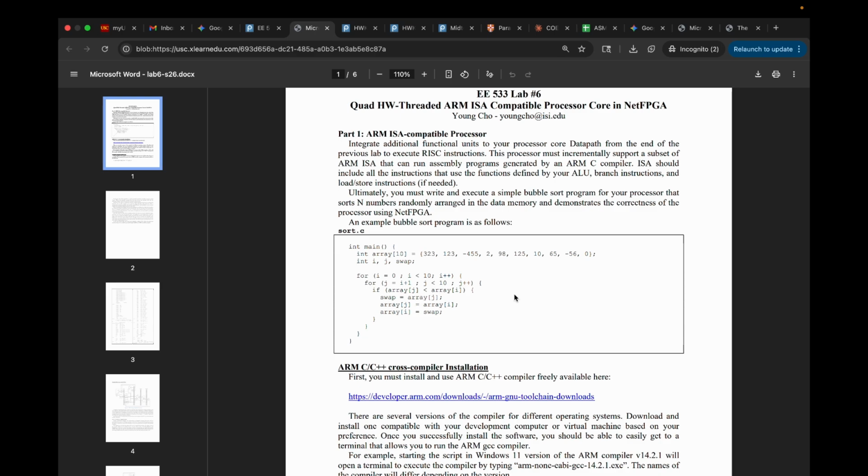In particular, pertaining to the data-processing (DMI) instructions, we followed the exact 32-bit split up. That is, the first 4 bits are for the conditions, the 16 conditions involved, followed by the type of instructions used, the opcodes, etc., and the NZCV flags, which update accordingly when the set bit is set, or for certain instructions like compare, CMN, etc. Irrespective of the set bit not being set, the flags are going to get updated.